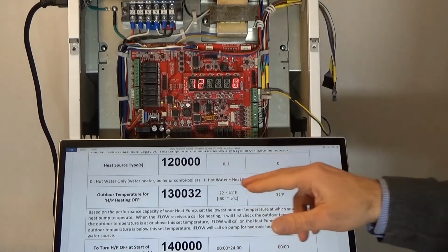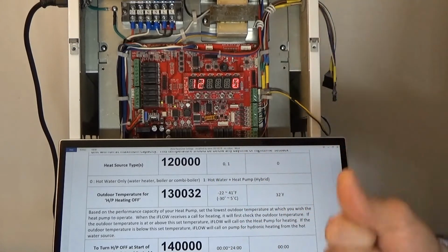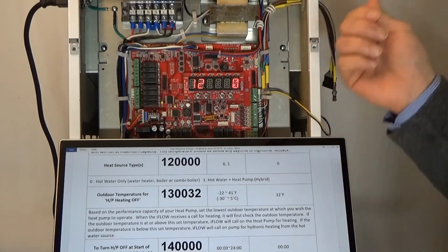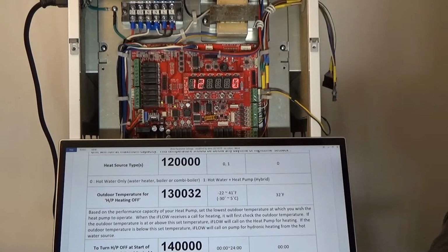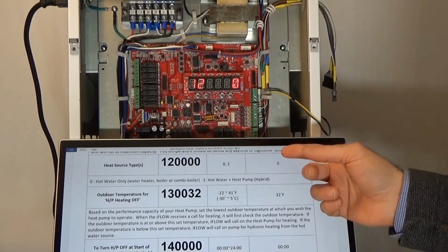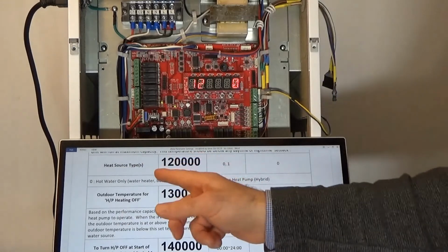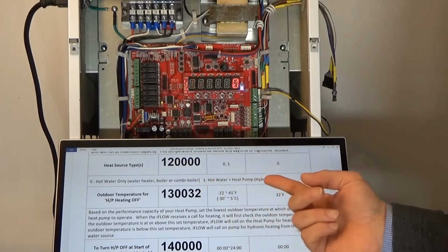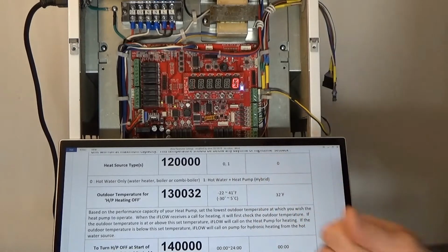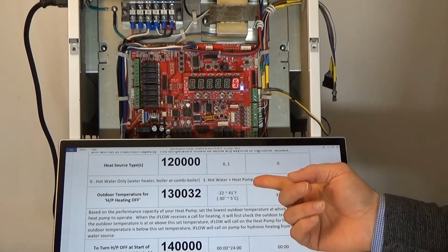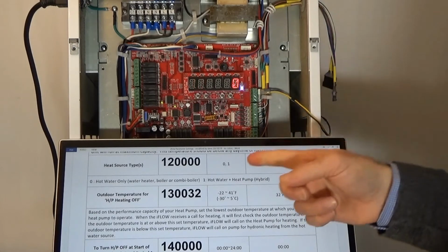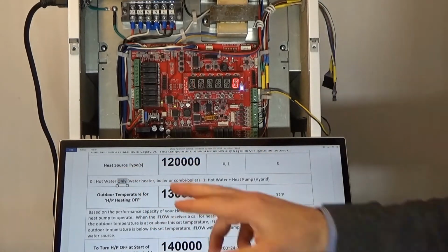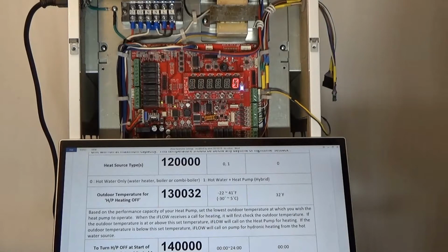When you have a heat pump, you must also remember you need the DH evaporator sensor temperature connected to the suction line near the evaporator to be able to detect the reversing valve operation. If you don't have that, your heat pump won't run, so hybrid mode won't run properly. Even if you have the heat pump but you don't have the DH evaporator sensor temperature installed yet, then you might want to run in hot water mode until you get those proper components connected and wired in.